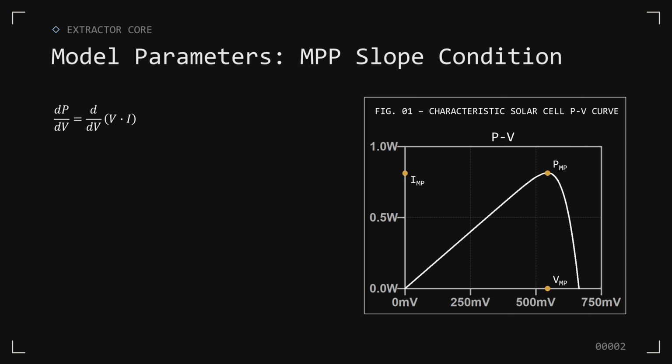As mentioned, we can take the reciprocal of the result to get back to dI over dV and plug in the 2 datasheet points for max power, VMP and IMP, into the equation, since we're evaluating it at that point. So what we want to do next is get rid of the I0 term, which is easiest to do if we also replace the exponential term. Together, these 2 terms define the recombination current flowing through the diode at max power.